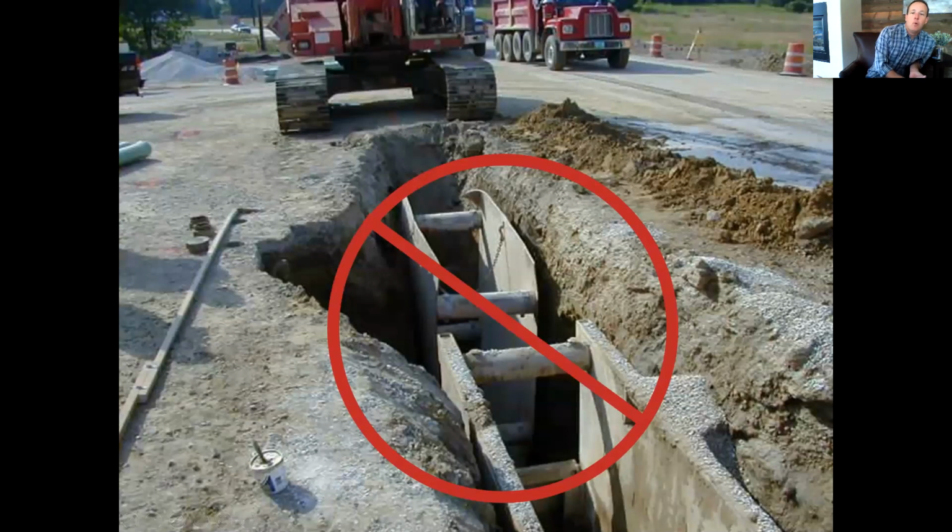Here, we do not allow a person to walk between two trench boxes if there is a separation between them. So this one has a 2 or 3 feet separation. It's hard to tell from the picture, but if a worker needed to go from one trench box to the next, they would be at exposure at that point. So this is not an acceptable situation if people are moving from one side of the trench box to the other. Now, if they're working in one trench box and then they get out of the trench and go over to the other trench box and back into the trench, that's acceptable.